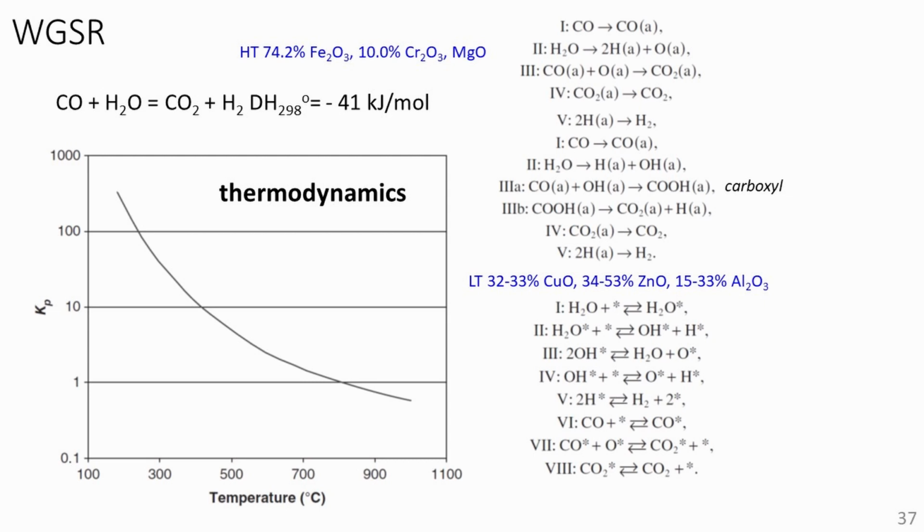The underlying reaction of this process step is called the water gas shift reaction. According to reaction enthalpy, the water gas shift reaction benefits from low reaction temperature. However, kinetic limitations are a critical issue. Hence, the process is conducted in two stages: adiabatic processes with a high temperature shift stage and a low temperature shift stage.